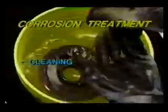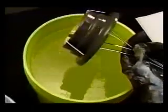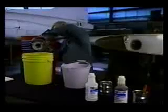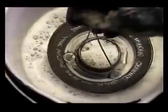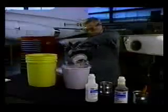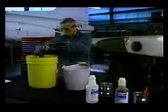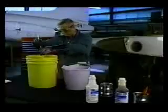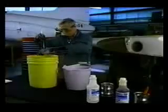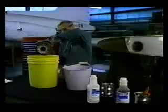When all the corrosion is removed, remove any residual paint, paint remover, and corrosion products by washing the surface with fresh water using a nylon bristle brush. Then remove any masking material and wash the entire aircraft or component with cleaning compound. The cleaning compound should be mixed to the manufacturer's recommended dilution. When finished, rinse the area again with fresh water to remove the cleaning compound. Be sure to remove all stripping compound from any nooks and crannies on the aircraft, because the stripper will adhere to the surface and start new corrosion.